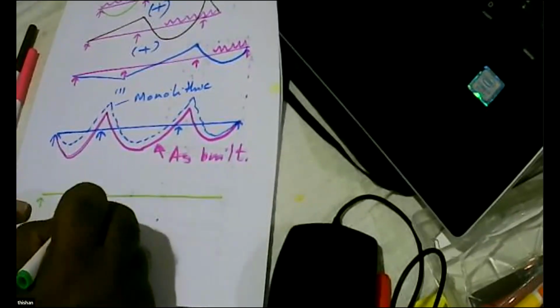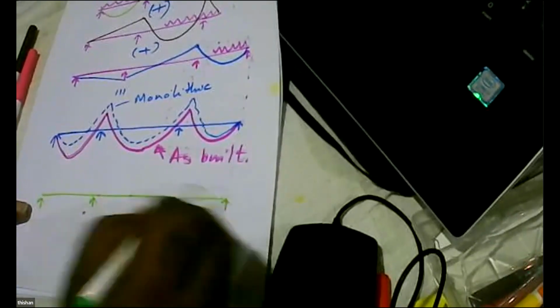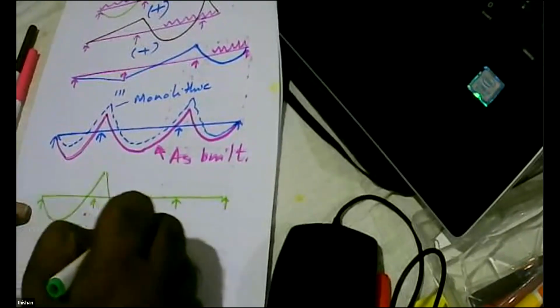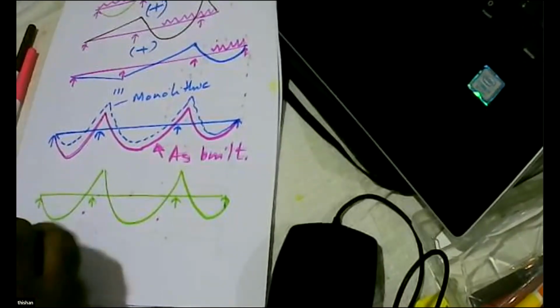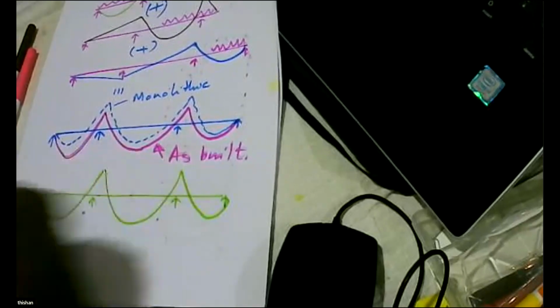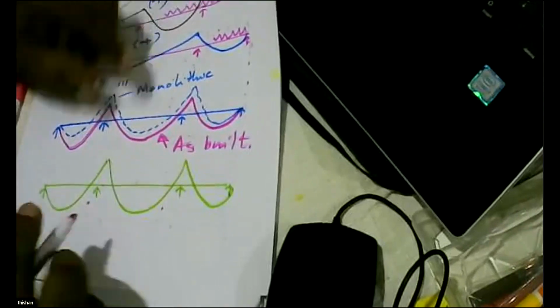But the problem is not as simple, because you can see now, if you look at one diagram like this, you get certain curvatures. Now what happens when you are doing construction? I need not have the same curvature, because I have considered only this. So the curvatures can be different. Because curvatures are different, we are casting not the monolithic, so we will have something called locked-in stresses.